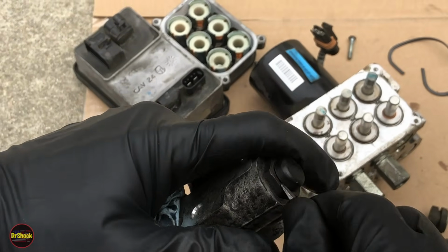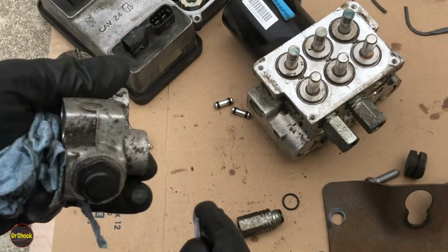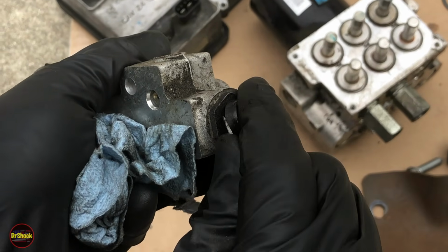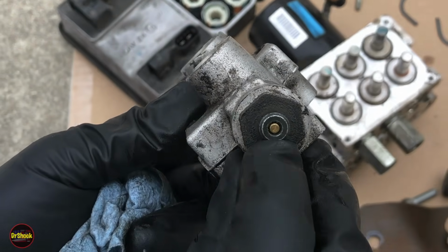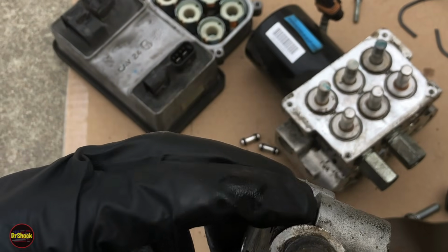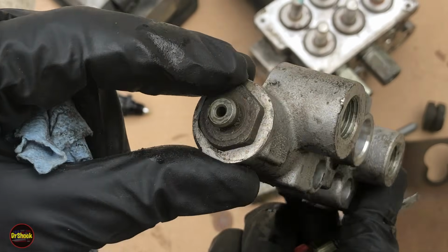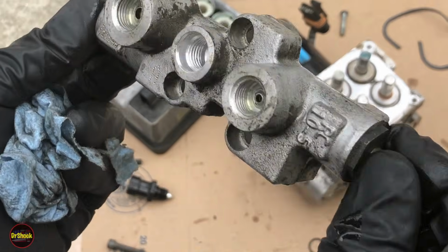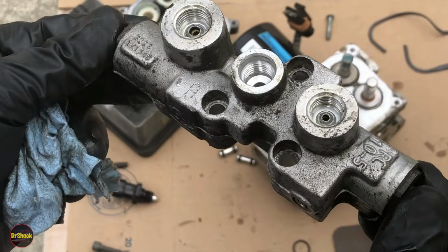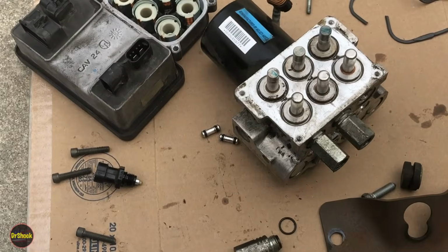This is on the side of the combo valve, very similar. It has some covers. These are the valves when you do an automatic bleed. You'll see one has a plunger visible, the other does not. That's normal. This is another thing you want to see, that it's not full of corrosion and that those covers have been in place on one of these that you're looking at. So anyway, I hope this teardown helps you out.